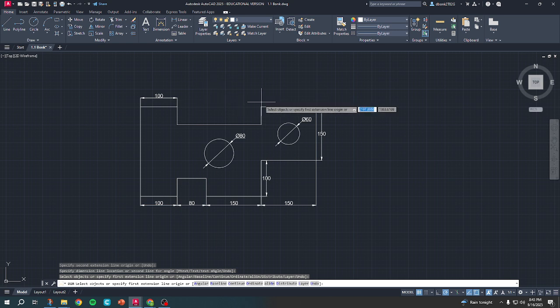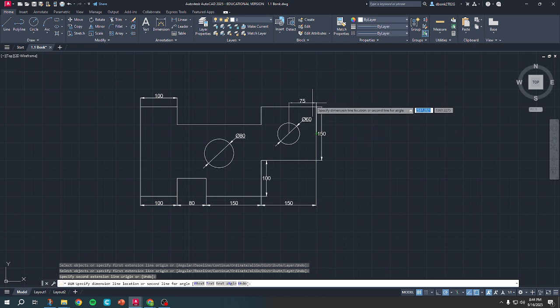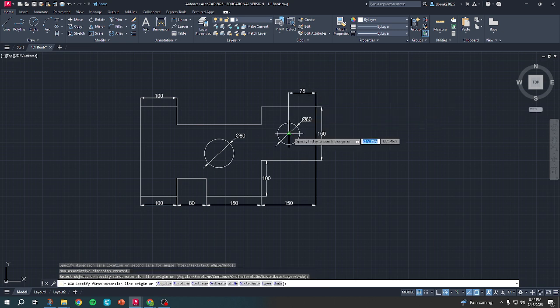There's actually not a dimension right there. On the drawing itself, there are measurements where they show you the placement of this. So you click that center point of that circle, click an edge, and do that.